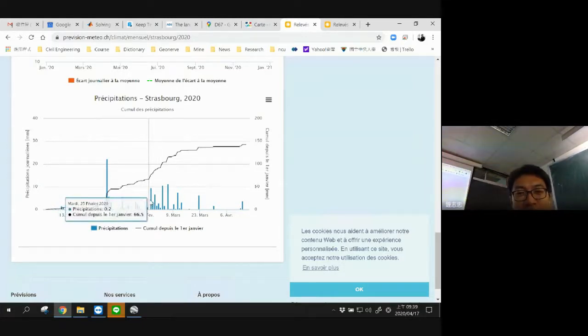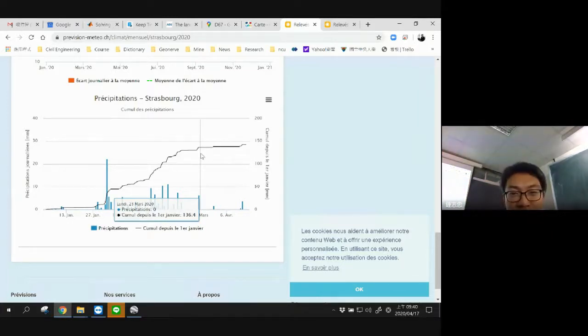You can see the accumulated rainfall is very big, up to maybe 70 or 80 millimeters at that time. After the rainfall on this day, the landslide was triggered. I think this is a major reason why the slope failed. So thank you for your help to identify the cause of the landslide.